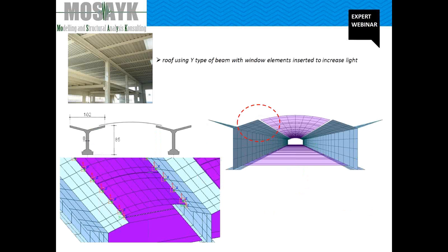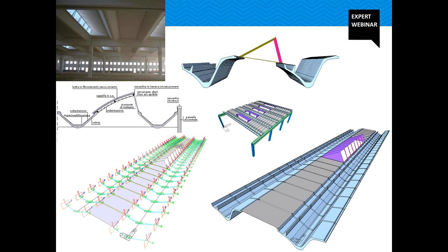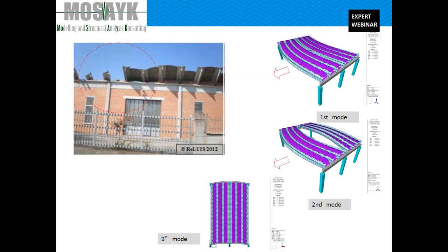If a window, a non-structural element, is placed on the roof between the roof beams, a refined model including the link interaction should be used. In this case, for example, this is a second case of window. In this case, we are able to capture a flexible roof behavior with a classical non-synchronous behavior after an earthquake.